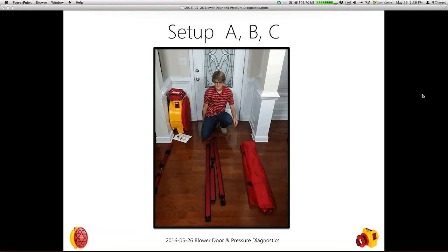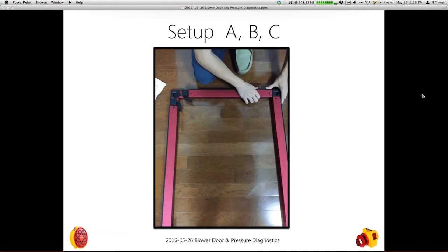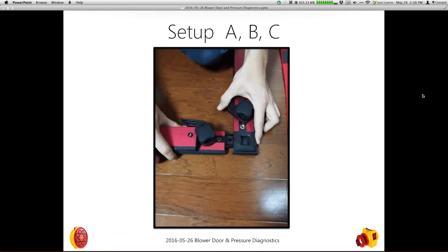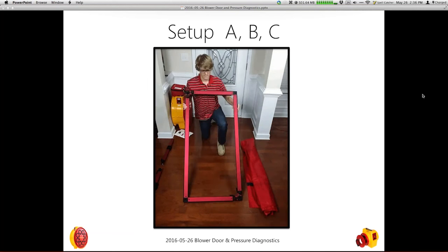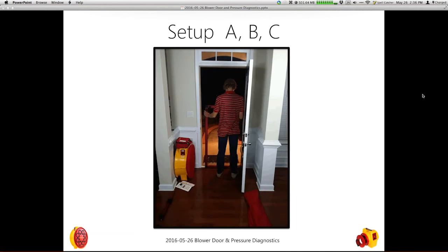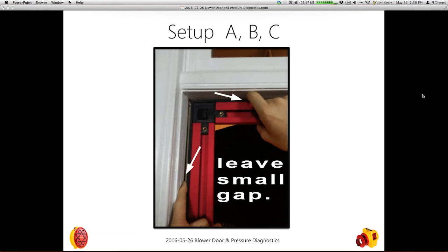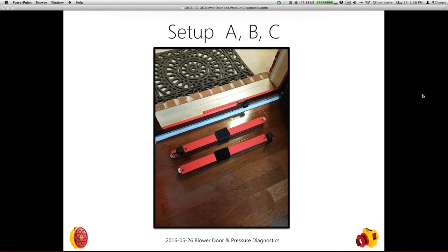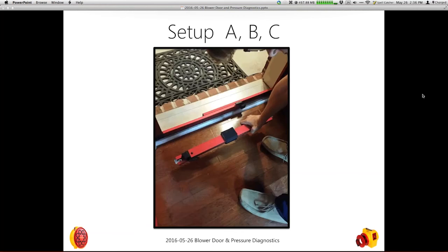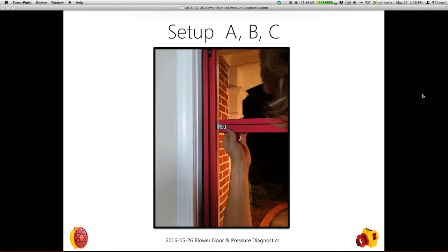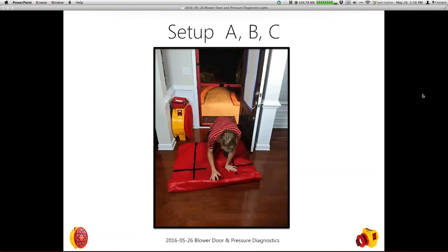It'll go up to around 97 inches tall. I think it's 42 inches wide. And the bottom's got a little track or a little slot where you can put the frame into. Now my son Jack's putting it in the window, securing it. These are all common procedures we either recommend or you should be doing. You know, pushing your thumb across the crossbar and tightening it, engaging all of the cams that are around. Whatever system you use, I always encourage you to follow that exact same one every time and pull on the frame to make sure it's not going to pop out.